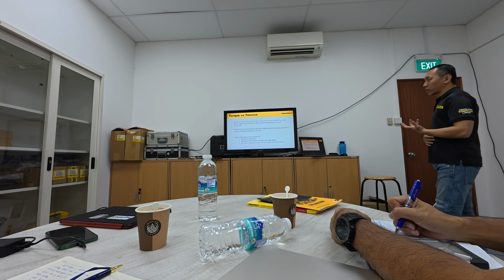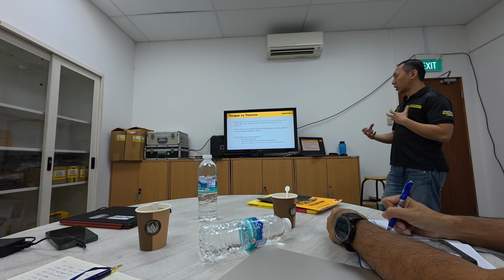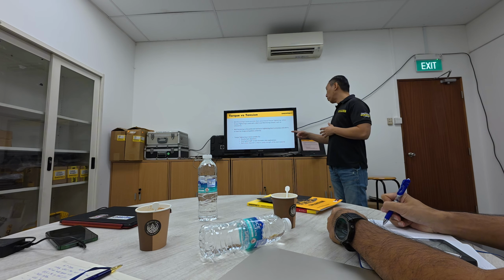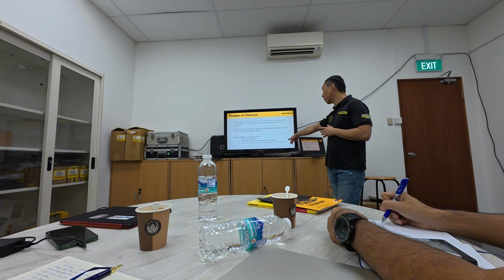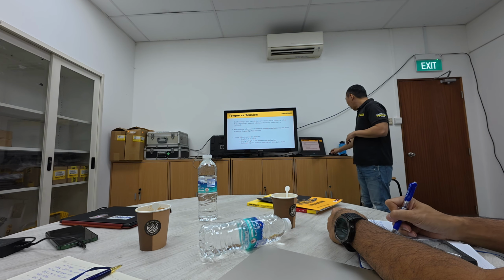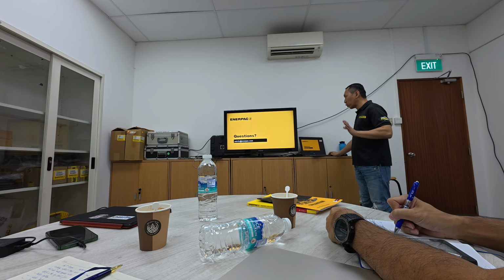Torque tightening is usually suitable for smaller bolt diameters, or a small, short grip length, meaning the stud is very short, or where the bolt stretch is quite close to the yield strength of the bolt material. So that's bolt tightening. Any questions regarding bolting theory?